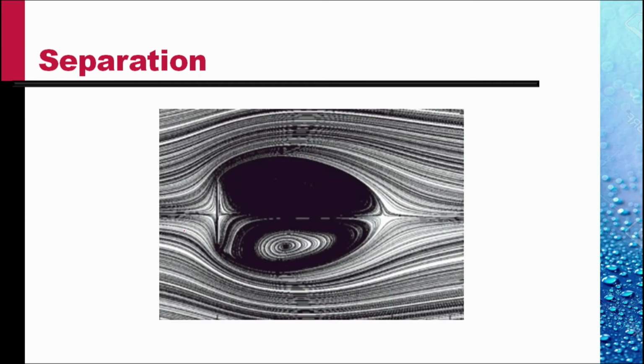Similarly, we have this plate held perpendicular to the flow. The flow separates at this tip, because if the flow was to proceed down the back side of the plate, the pressure would have been increasing, and the flow separates, forming two large attached vortices. Because the Reynolds number is not very high. If the Reynolds number was very high, these vortices would have been washed down and we would have a region of turbulence in that place.